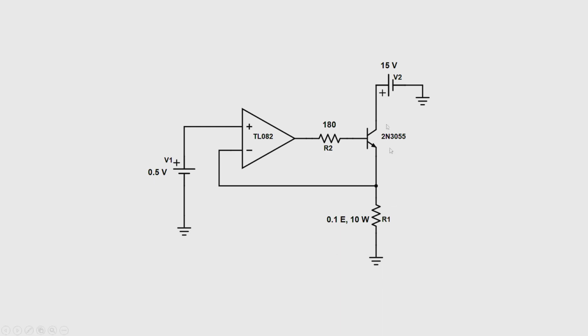Based upon the principles of a transistor, we know that the collector current and the emitter current are approximately the same, related by a proportionality constant alpha. As a result, the collector current will also be approximately 5 amps.